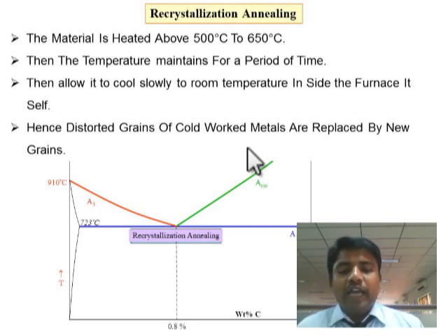While you cool it, what happens inside is that the structure refines and forms into a new structure, and gets bonding from one structure to another. If it is not done, the dead cells between the structures will not get bonding strength. There you can see that vacuum space is created. If a load is applied to that part with the dead cells, there is no bonding strength and the material fails. So we have to refine those dead cells. You go for the recrystallization annealing process.